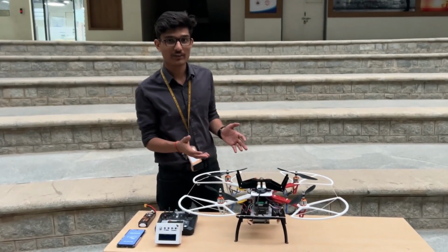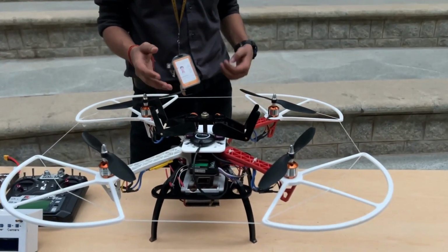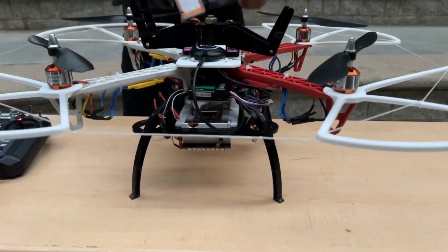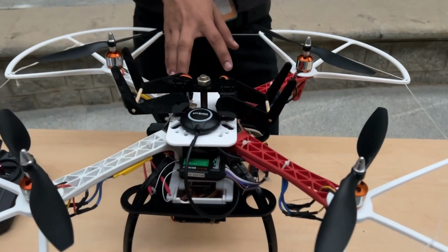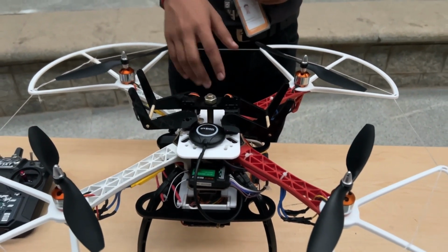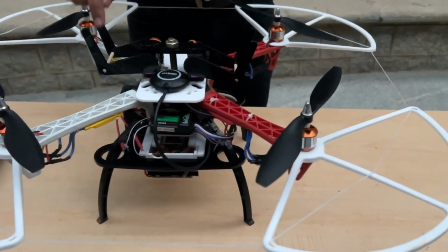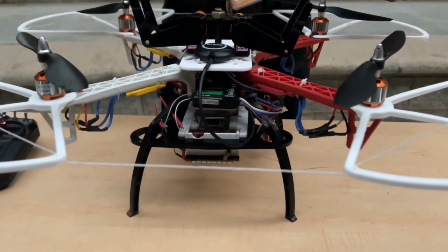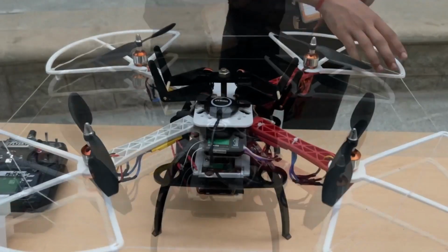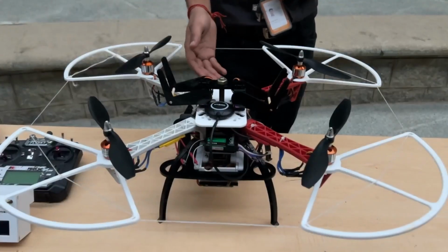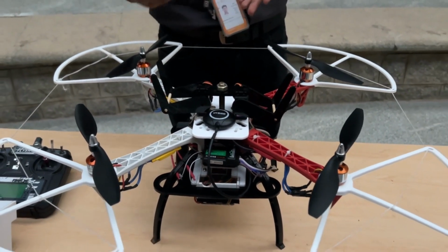Now talking about the hardware, there are two main components. First is the autonomous drone itself, and second is the ML based attachment. So let us first talk about the drone. The drone is flown by a flight controller, which is connected to a GPS module. The flight controller is connected to 4 ESCs. The 4 ESCs control each of the BLDC motors, which are 2200 kV, and there are guards for safety. Then we have a buck converter to change the voltage from 12 to 5.